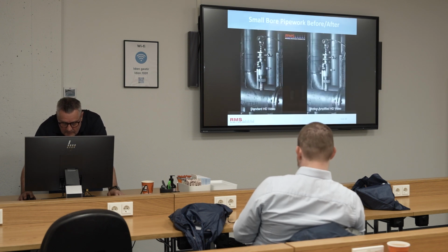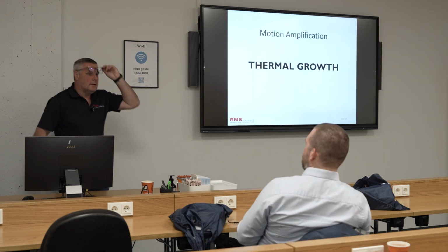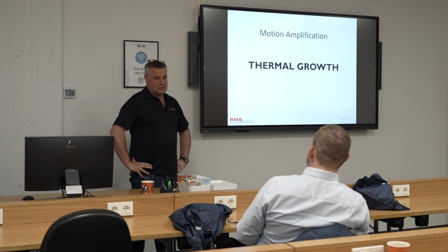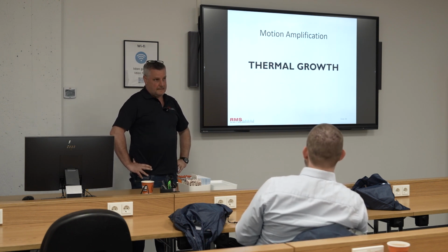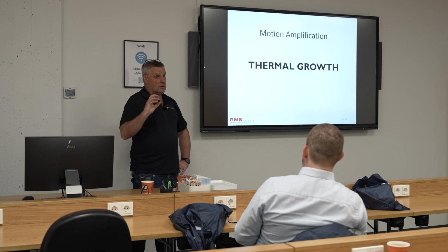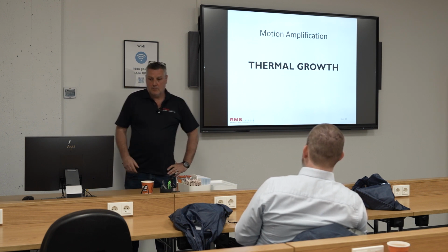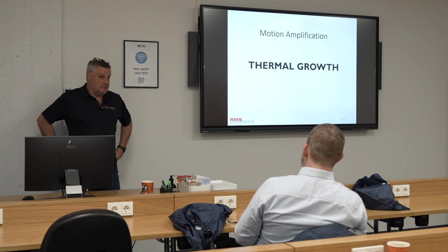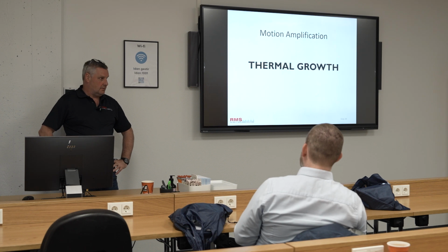These guidelines from the Energy Institute, is it an international standard? Yeah, it's an international standard. There's a proper specification for it all, for small bore pipework, large bore pipework. It's the only thing we've got from a vibration perspective, really, to reflect industry standards. So that's why we use it. There's various standards out there for vibration as well.